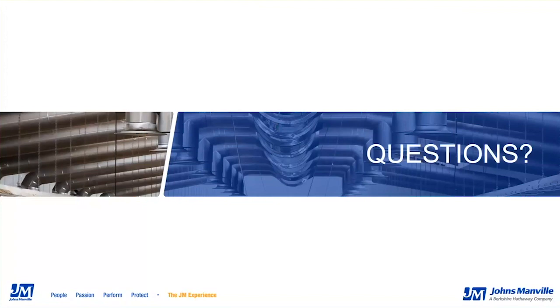I would say it depends on the thickness of the material. As I mentioned in the presentation, thickness is a large factor in the acoustical sound performance of the material. So a thicker blanket may perform as well or better than a similar board product if the thickness is much greater than the board product, for instance.